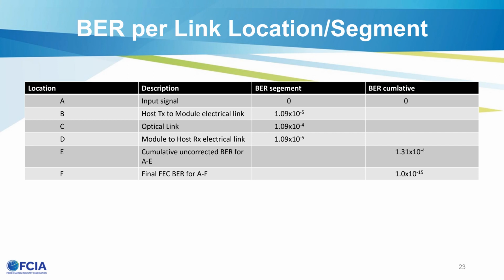If it goes beyond that, it's going to be an uncorrected FEC code word, which starts to give you an idea of the link quality. You'd like not to see them, but in fairness, they are completely recoverable, and you would need a pretty large number of them before it actually affects your throughput. So the parameters now are a little different. It really is no longer the simple bit error rate. It really comes down to what are the FEC corrected and uncorrectable code words.